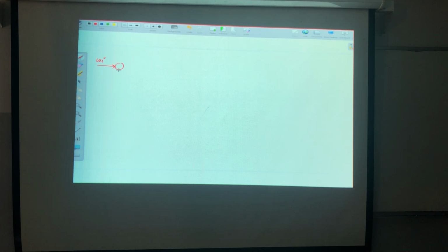I will compare it with the actual omega R. Then I'm using a PI control, which is KP plus KI over S. Then I will have a limiter. So this will be omega slip. Now this omega slip will go to the constant flux relation, and I will get from it